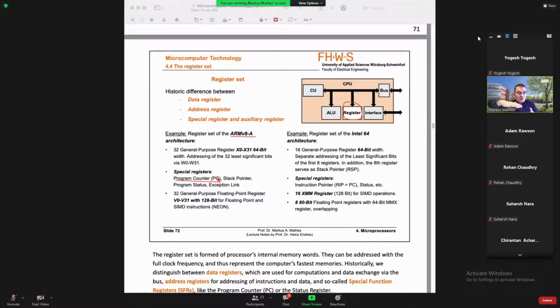So I skip all commands in between, and I invoke the subroutine at a different address. This means that if I use branch link BL, then the program counter has to be modified. The program counter has to be set to the starting address of my subroutine.